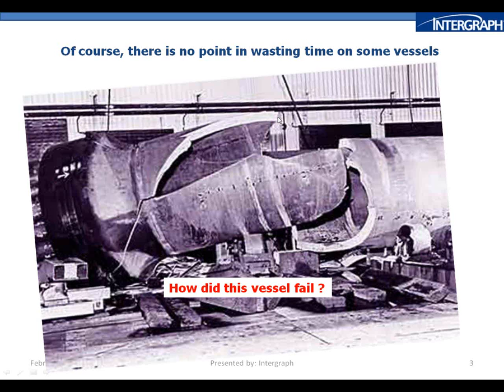Now we consider re-rating a vessel. There are a number of reasons why we re-rate a vessel. It might be a change in temperature. We might want it in service to experience a change in pressure. The vessel may have suffered some corrosion or erosion or metal loss. A repair has been done, and we have to reassess the vessel after repair. There are any number of reasons why we would re-rate a vessel. We're just going to consider really one reason during the course of this discussion. First, we consider metal loss.